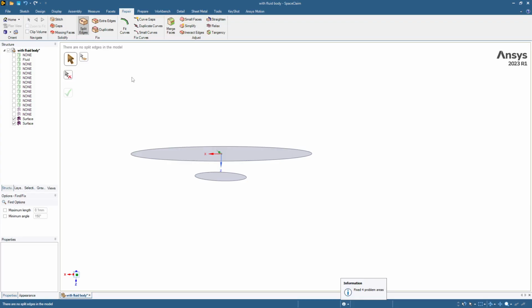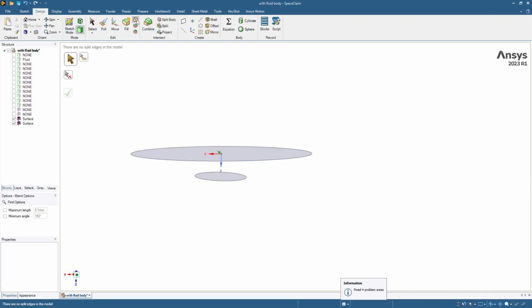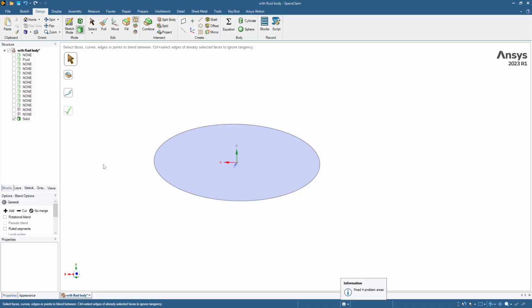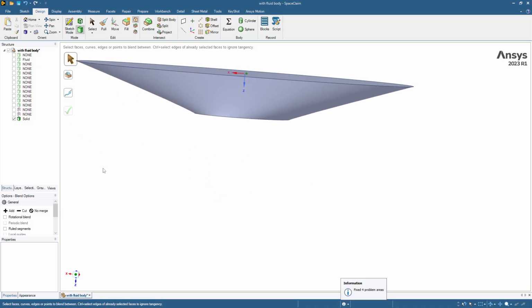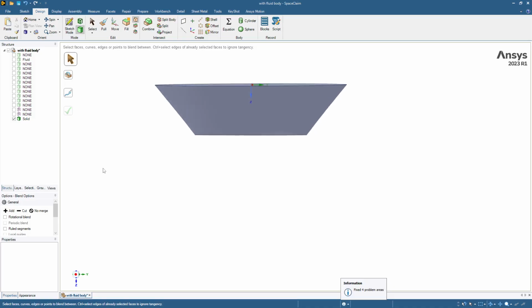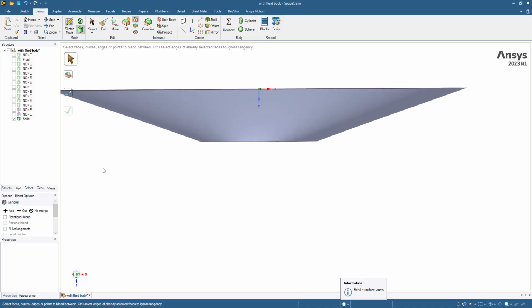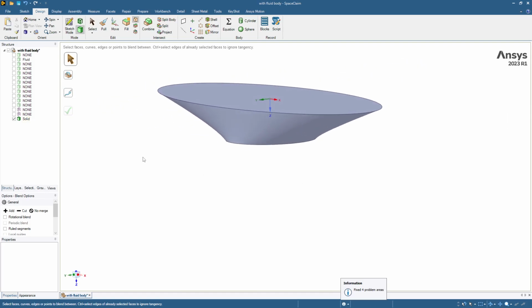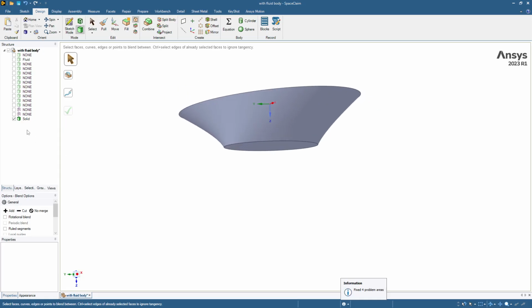And we can recreate the funnel, is what I'm calling it, using the blend tool. The blend tool lets you pick one edge and then control key another edge, and now puts a much more uniform shape. And as we spin this around, you can see it comes more directly down to the edge. There's no wicked hook. So I'm going to call this a more true shape of funnel.